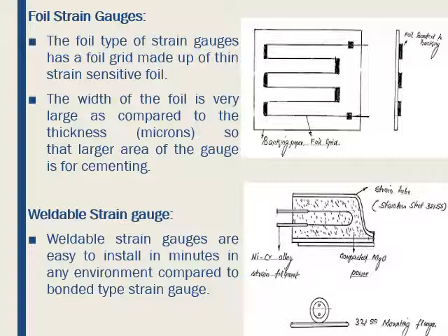The strain element is insulated from the tube with highly compacted ceramic insulation. This kind of gauge is subsequently spot welded to structures under test and provides the bonding to transfer the strain.